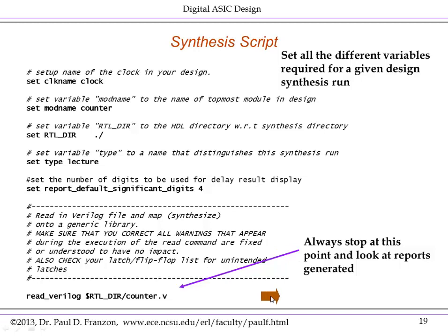We then do the actual read_verilog counter.v in the current directory. It's important to actually stop at this point. What I suggest you do, if you're using Design Compiler, is cut and paste up to here and stop and look at the results, because the read is more than a simple parsing of the file. It maps the design into some generic logic and checks for problems and errors.